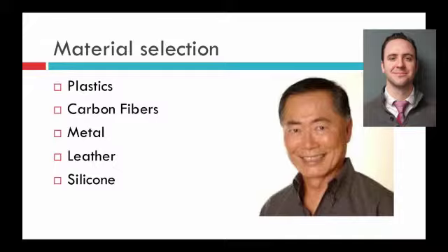There's this design that was made in Canada called the ESR, which has three layers of plastic inside of it, and it's actually very dynamic. It's very flat in the posterior aspect, and what that does for us, let me try to lower that a little for you, is as you bend your knee or come forward on the plastic, it loads the material, so you're adding energy into it, and then when you unload it, that's when it springs back and gives you that energy return. So it's quite possible to get energy return from polymer systems, but very specifically, this is a very rigid system.